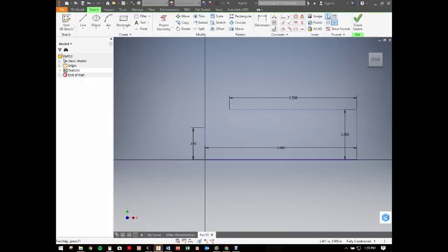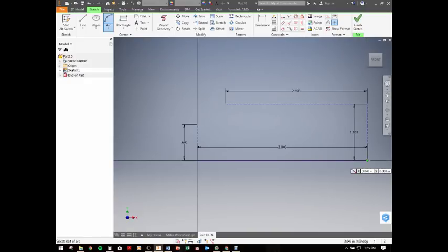Okay, so I don't want construction lines anymore. I'm going to go to arc, start at this point here, wherever these points can join, and here. And now as I drag my mouse up and down, you can see which way this arc goes. I want this arc to bow this way. I don't want it to be this way. And then I just type in the radius of my arc. So this is 6.